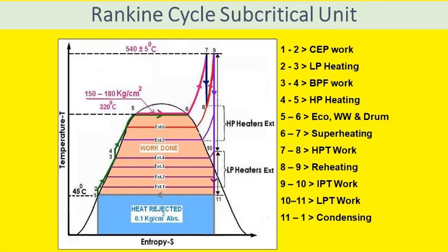Now, from 5 to 6, it represents the various stages of heating in the economizer and water wall. And as you see, our drum, the steam drum or water steam drum, is placed outside the heat transfer zone. So water in the drum is represented by point 5 and steam in the drum by point 6, because both are in the saturation stage.